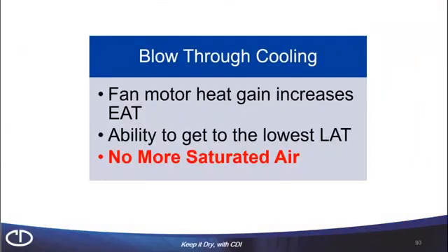The benefits of using desiccant drying for this sort of application, one is that we can go to blow-through cooling as compared to draw-through. That gives us the ability to put the fan heat in front of the cooling coil. The cooling coil is going to see sensible load only, and that allows for a much more efficient system.